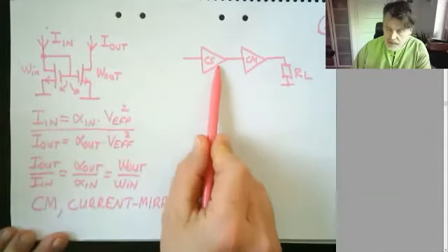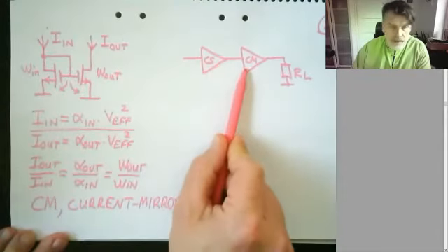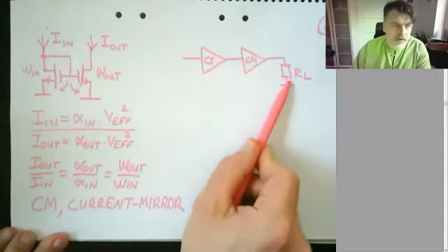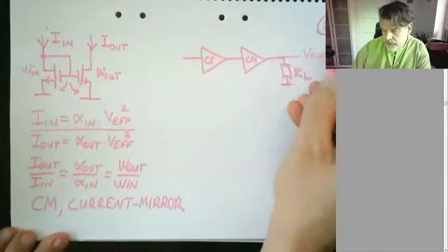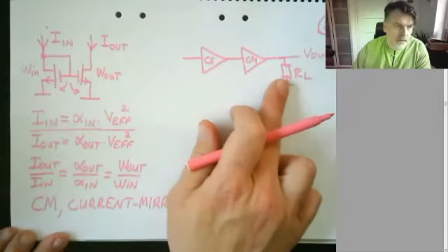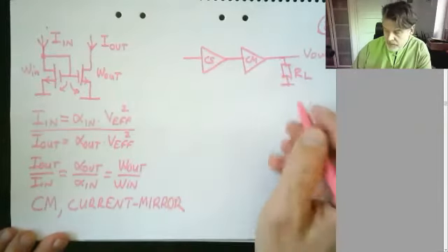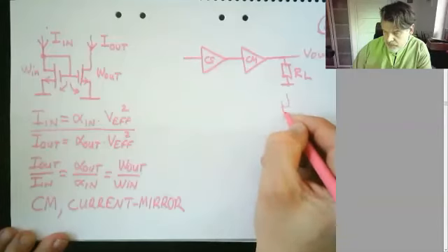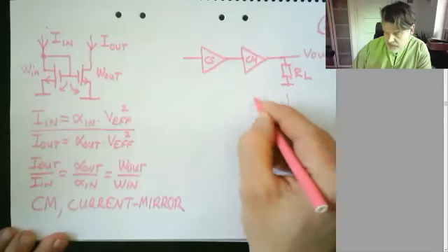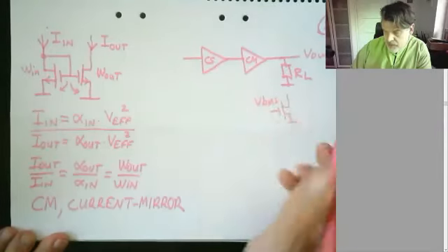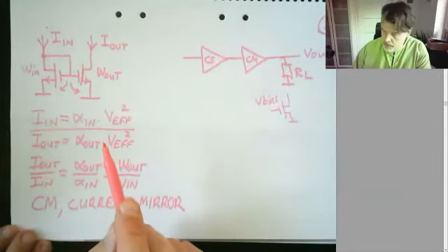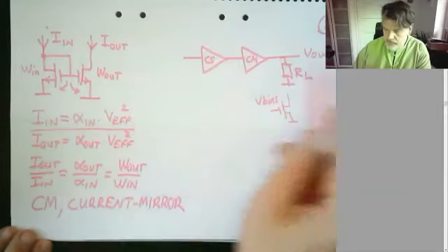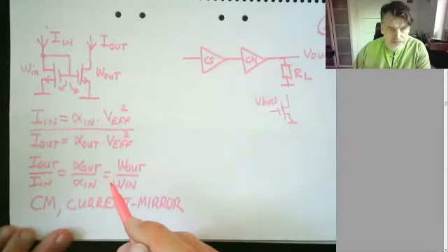So I will have gain in my common source, and then I can amplify the current, and I can terminate it over a load to get an output voltage. Or once again, I could terminate it over an active load also. I could put the transistor here acting like a current source at the output, and that will also give me high output gain then.